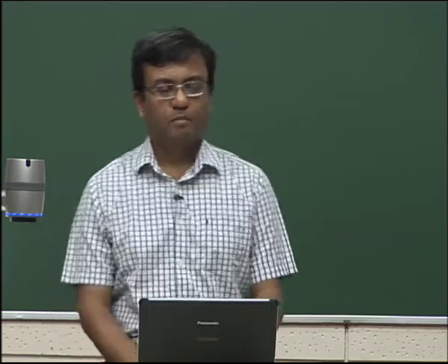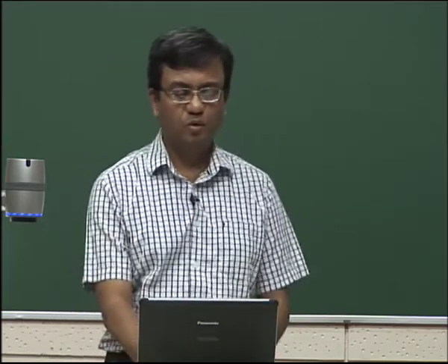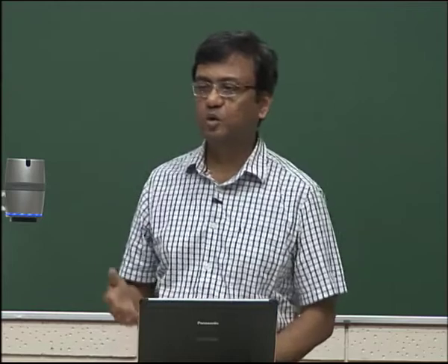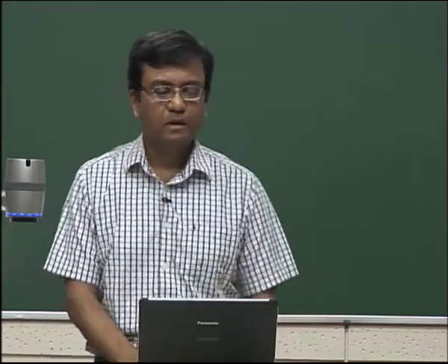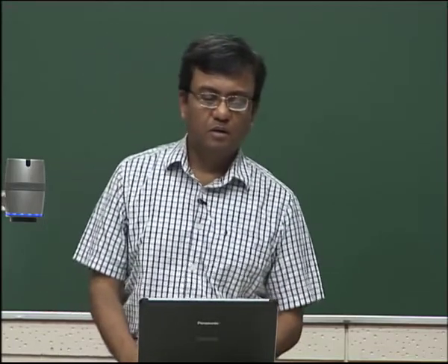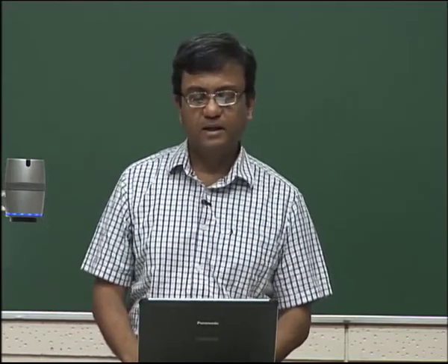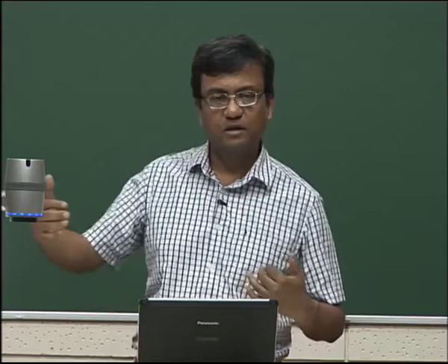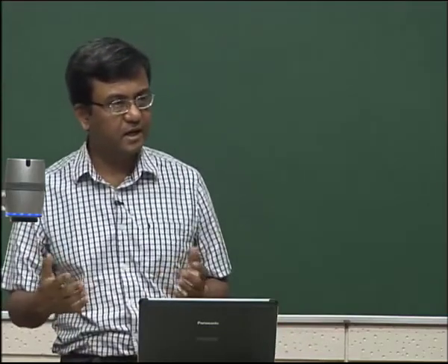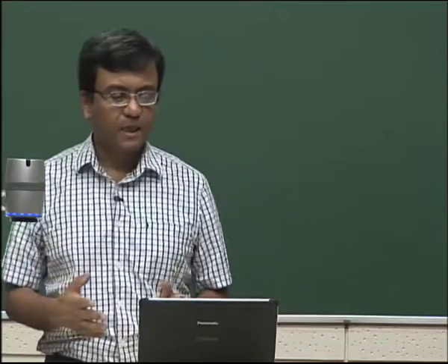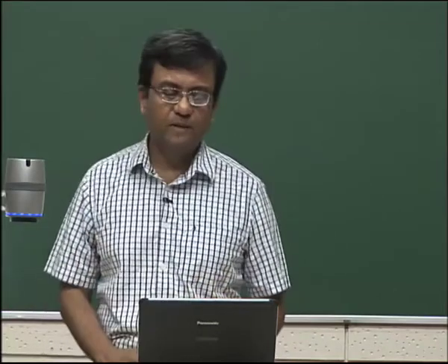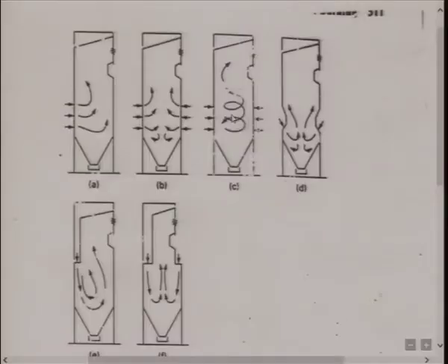All right, so this same thing is what we saw here. But in this view, if you look at C, you cannot see the 4 corners, of course. This is just a front view. So you can't appreciate the fact that from 4 corners you have coal and air coming and hitting an imaginary circle at tangents and then producing a flame ball. But here you can see the effect.